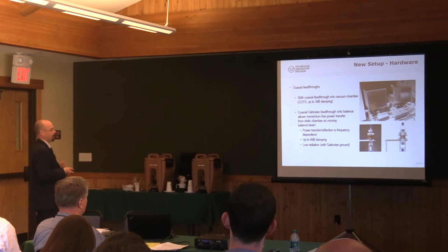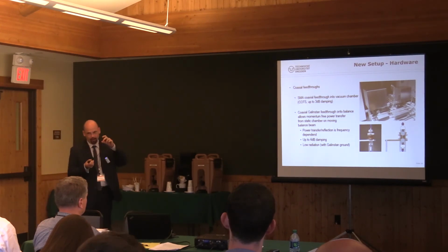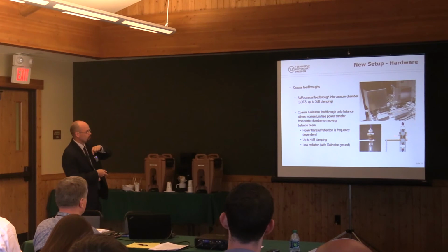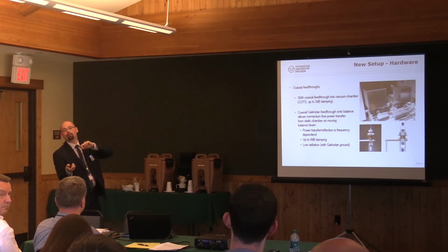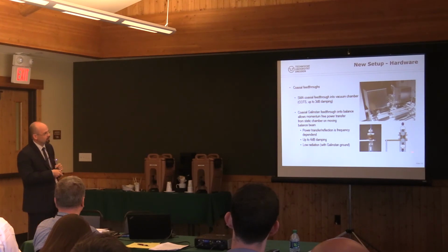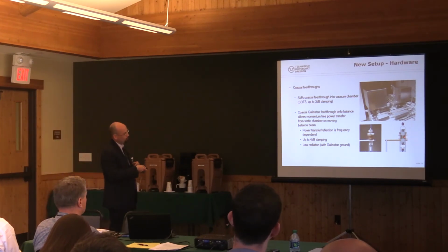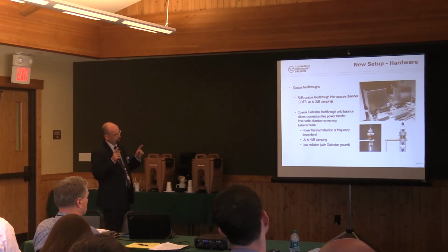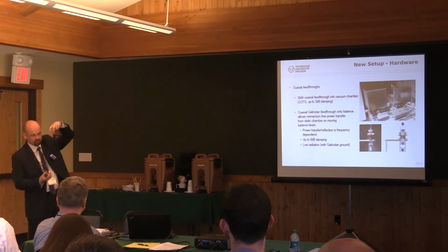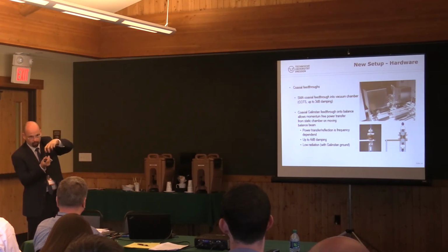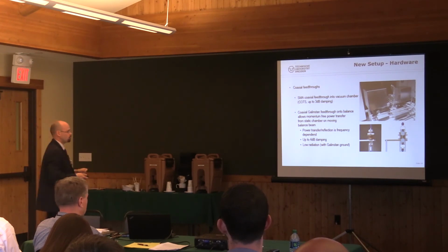So Matthias came to the idea to try to connect 2 N-type connectors with some, what's the material, Matthias? Copper. Not the copper, the plastics? PEEK. With some PEEK elements, and building 2 reservoirs, one for the shielding, for the ground, and a second reservoir for the power line. So we just used 2 N-type connectors, positioned them face to face very closely and rotatable.